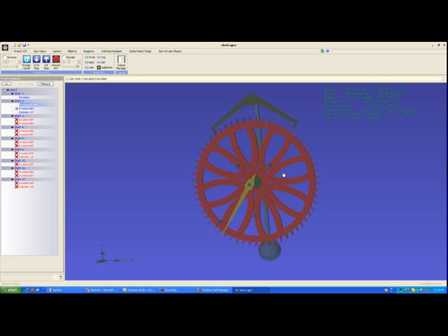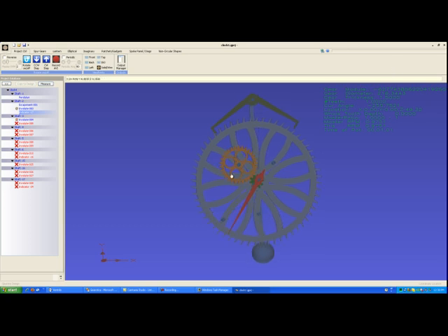So I'm going to add a gear to that. And what I did is I added a 30 tooth. If we look at that 30 tooth gear now, we can see by looking on the side of the screen that we have a rotation time of 3 minutes now for this gear. So we're well on our way to getting to a 1 hour rotation. I'm going to add a pinion to that. And again, I'm going to use a 10 tooth, because I like 10 and 30. They're nice and divisive numbers.